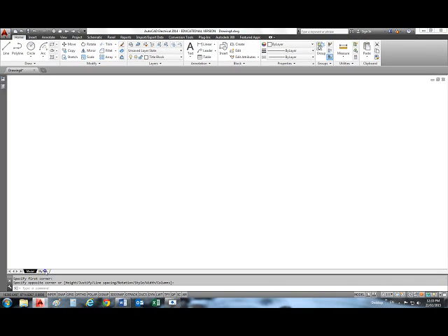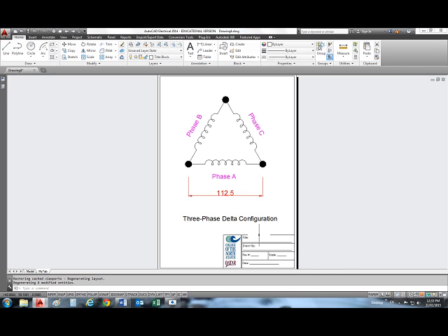Okay, let's go to my tab and make sure that on Paperspace, title block is actually placed on title block. See, now it's placed on part. The viewport is placed on layer 0. So we're going to say, make sure that you're again on Paperspace, Control A, place everything on title block.